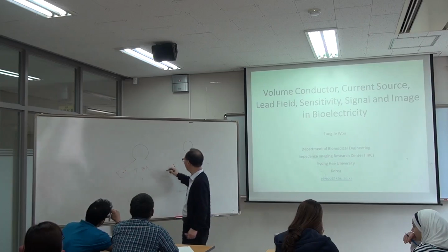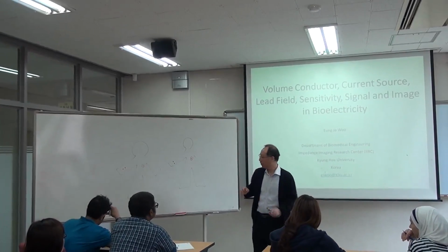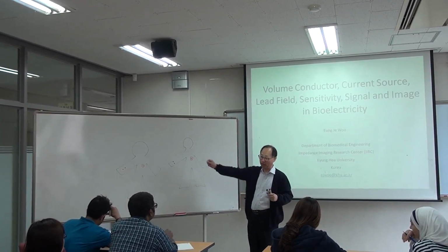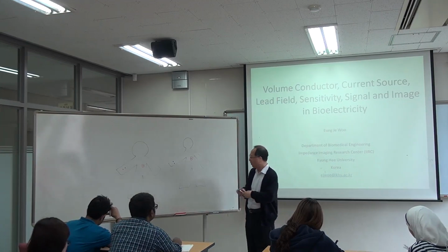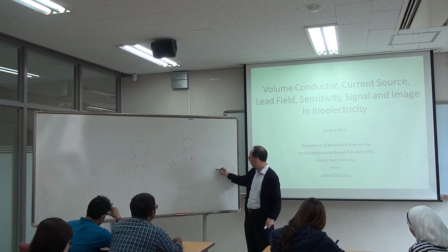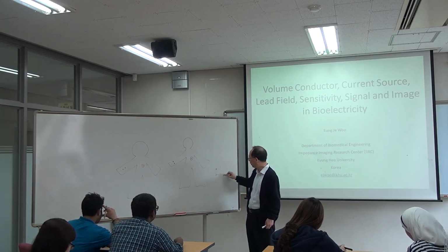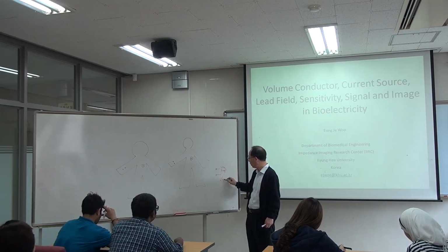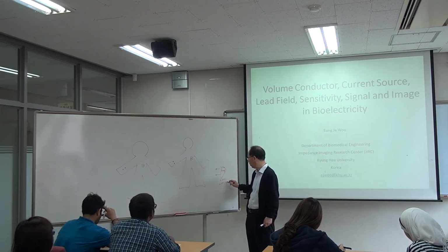So I intentionally ignored the reference electrode. Let's assume there's another electrode for voltage reference, the ground electrode. So we have 2 electrodes like this, and then we can construct an ECG amplifier with a gain of 1000 and a certain bandwidth.